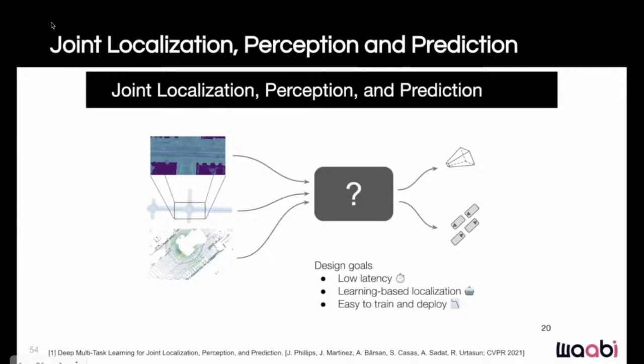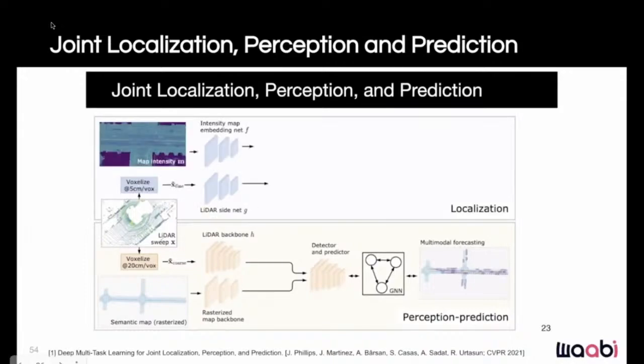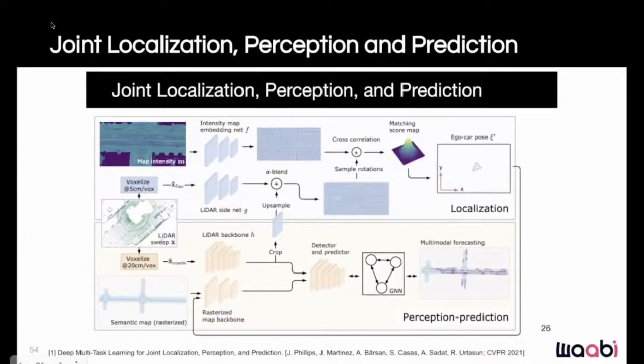The proposed architecture extends a state-of-the-art detection and multimodal motion forecasting network, the implicit latent variable model, with the ability to detect and correct pose errors with minimal computational cost. The pose estimation is done using a deep LiDAR matching approach over 3 degrees of freedom, x, y, and yaw, and the computed offset is then applied to the semantic HD map used in detection, forecasting, and planning.